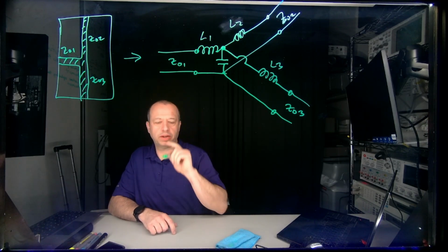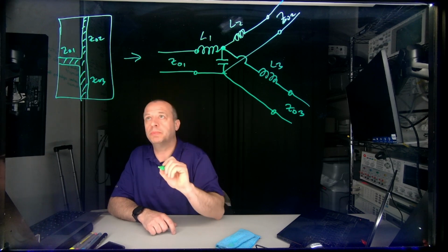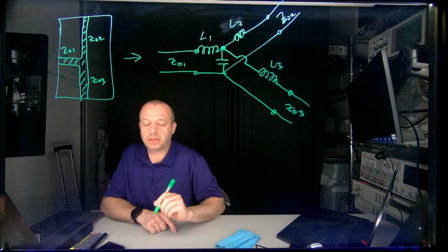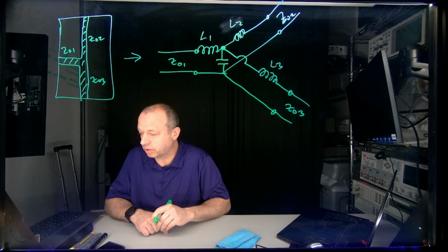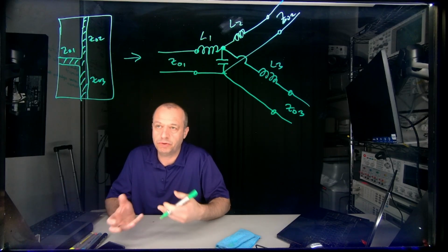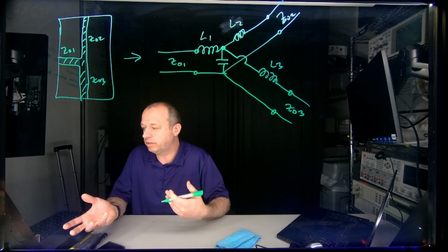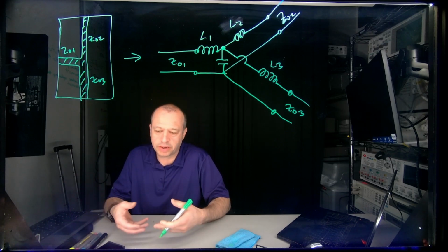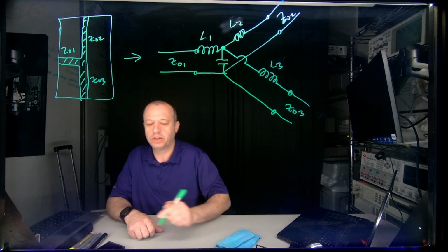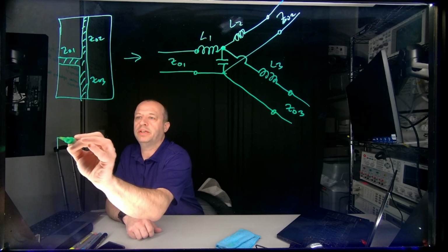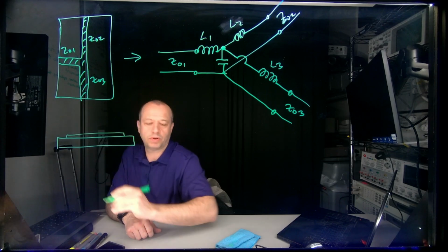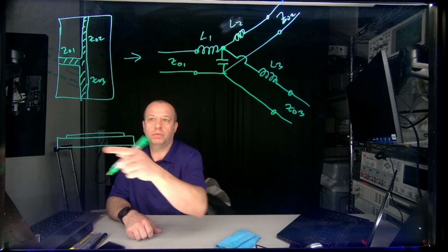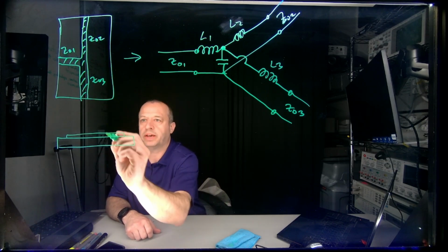The last one, and you'll see an example in your textbook about this one, mainly because even though we don't do this on a circuit board, anytime you add an SMA connector, you have a cylindrical transmission line going into a trace transmission line. So this last one is, here's your PCB with some copper pour on it, some design, whether it's this trace or something else.